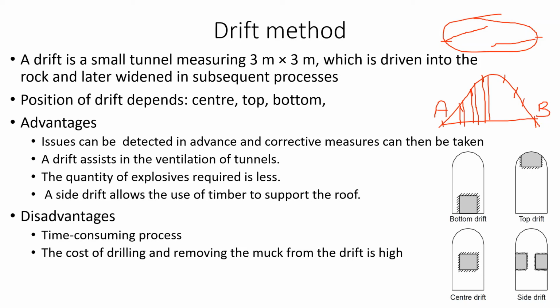So these initial tunnels will give you an idea about the strata that we are going to deal with, and also regarding the water table. So if some problems are there, then corrective measures can be taken to rectify that. So that is one of the advantages of the drift method. Another advantage is that once the drift is constructed, it can be used as ventilation for the further excavation or boring process.